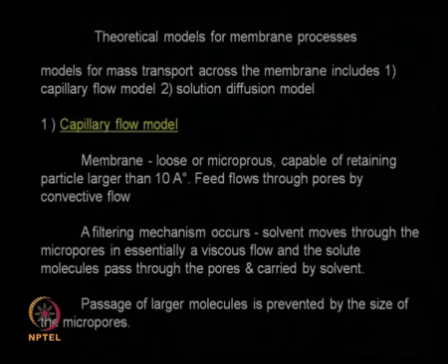Larger particles, of about 10 angstroms, are held back, and the solvent flows through the pores in a tortuous way, and very small particles travel with the solvent. So it is like a filtering mechanism. The solvent moves through the micropores by viscous flow, solute molecules pass through the pores carried by the solvent, whereas larger molecules get retained because of size. That is the capillary flow model.